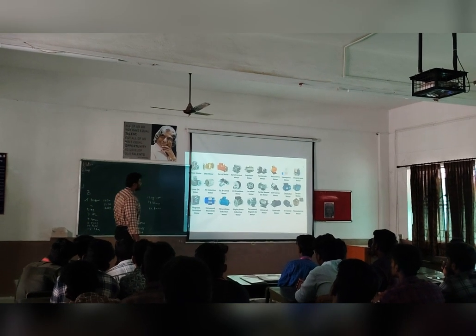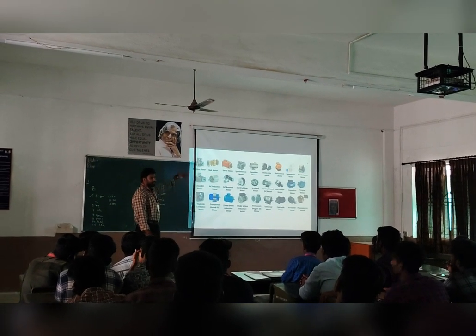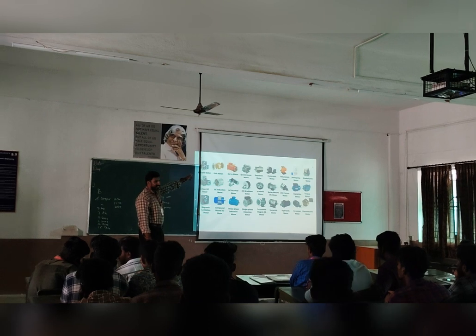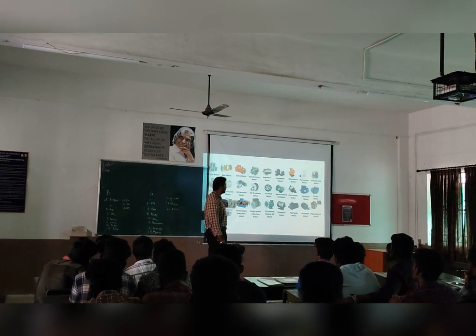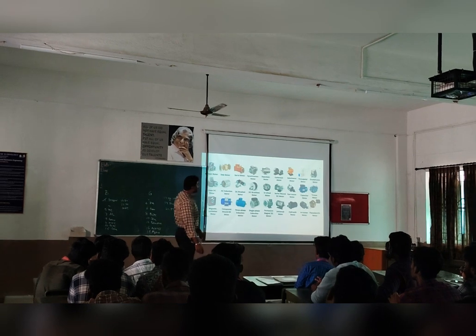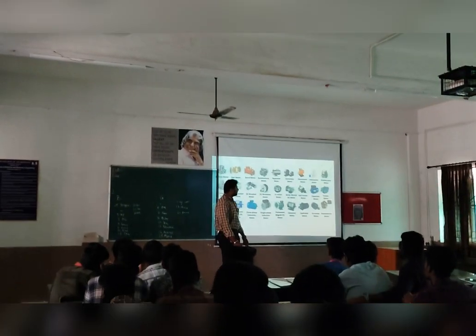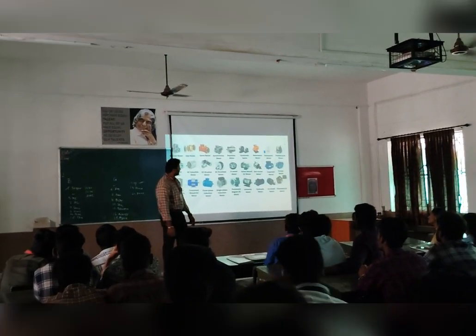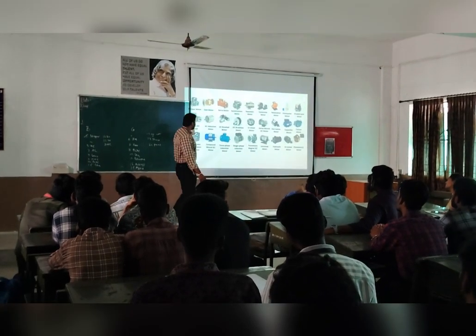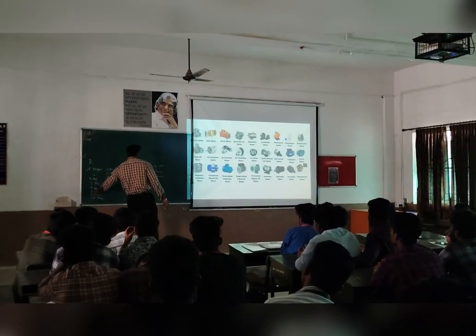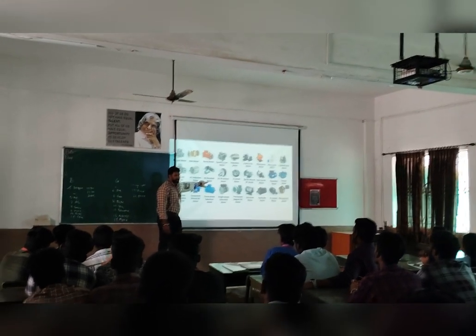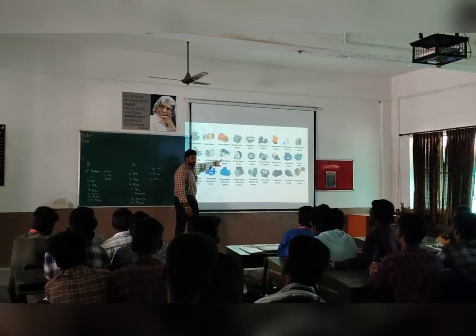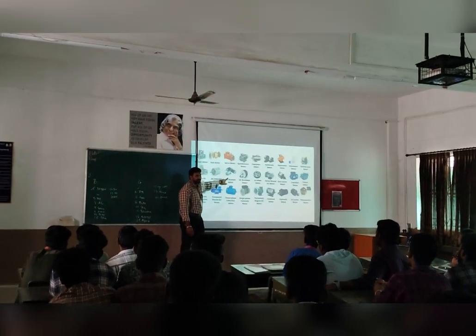And the internal spur gear, for example, will also be parallel, but here it is the internal gearing. The previous one was external gearing or external tooth portion, but the internal spur gear has an internal tooth portion. The gears of these two shafts mesh internally with each other as shown in the figure. The larger of the two wheels is called the annular wheel and the smaller wheel is called the pinion.